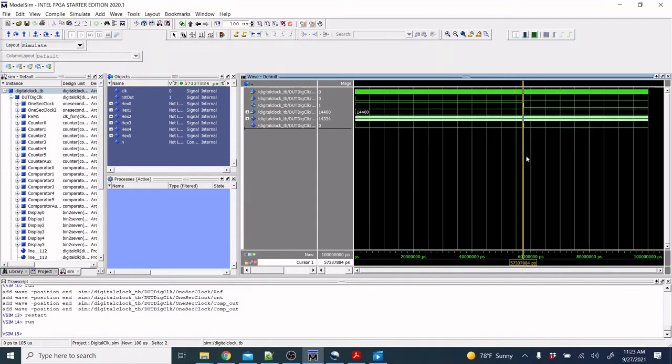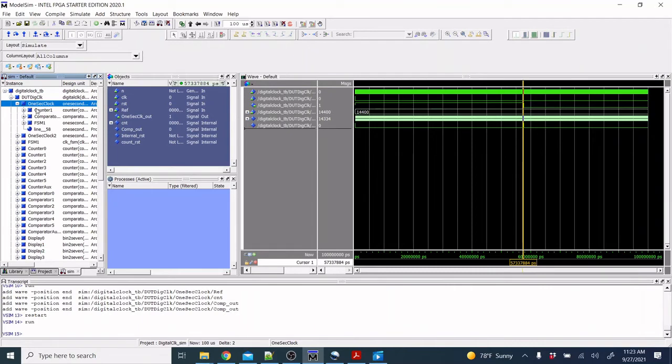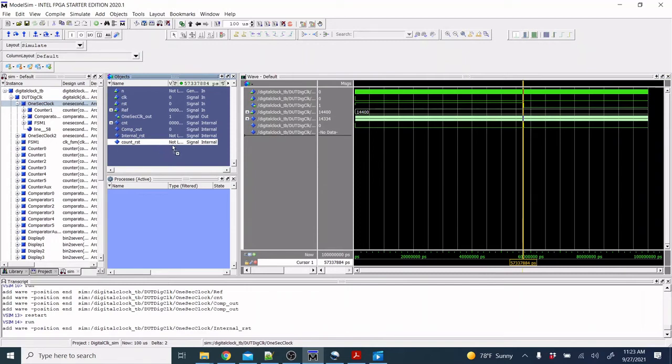But assuming your counter is not working properly, then we want to check if you have a reference connected properly and your counter is not counting, you're getting red at the output, and your comparator is not working. Of course, if your counter doesn't work, then we want to check that the counter is getting the correct signals. So we go again back to our component, and then we want to check that the counter is getting the correct reset.